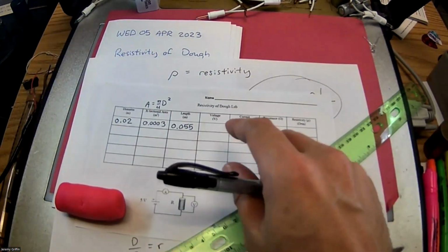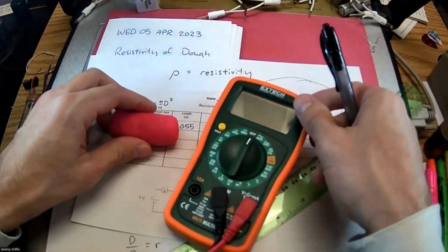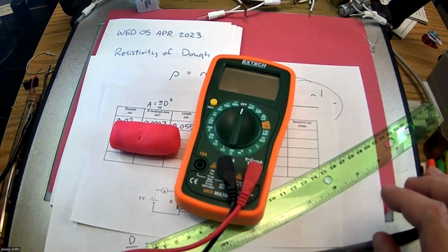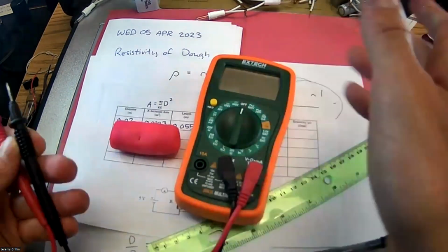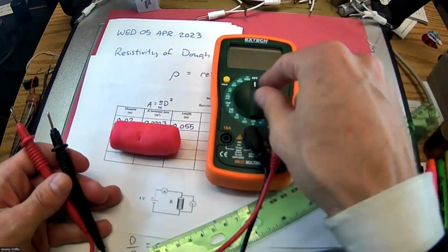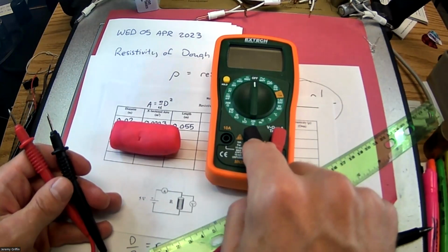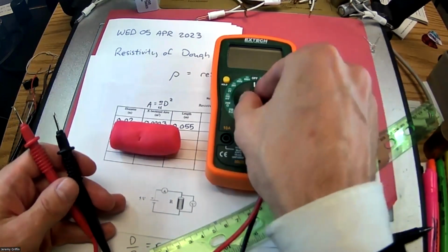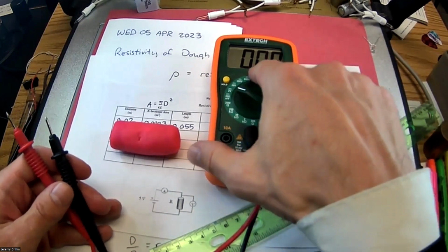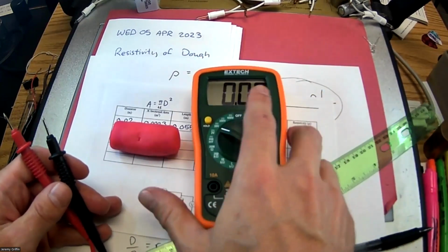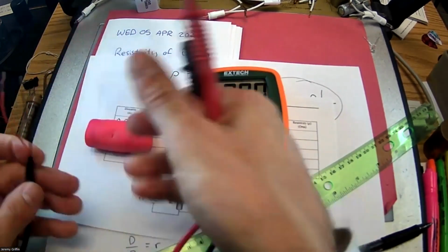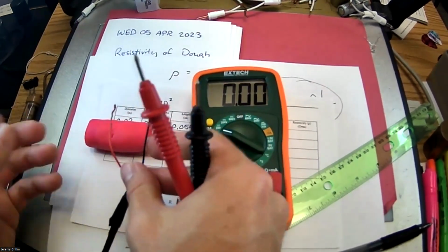Voltage. Okay, now we've got to break out this voltmeter. You guys remember measuring voltage in volts or current in amps? You need to do some different processes. So these are plugged in the correct way. The black one goes in COM, the red one, once it says volts, it switches over to DC volts. Get the decimal place in a good spot. Okay? And then let's wire this up. Now, you don't actually need an LED for this. I was just doing that to demonstrate.